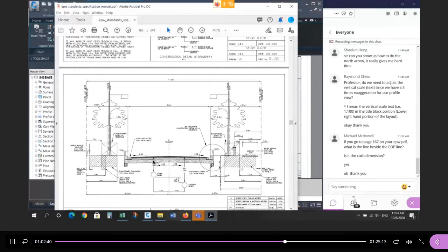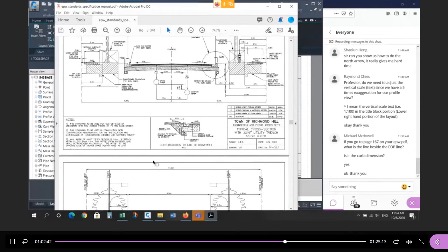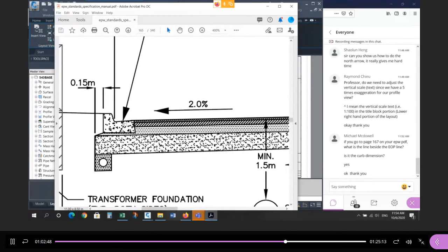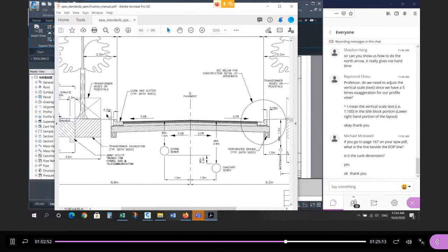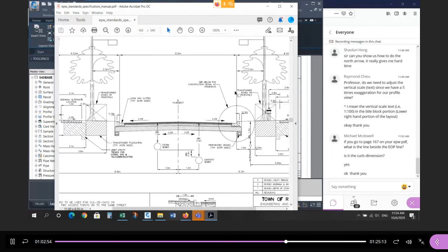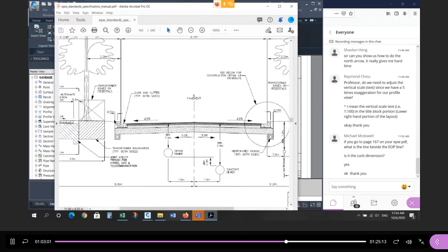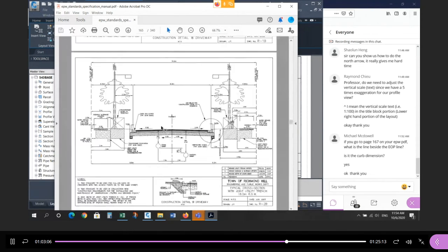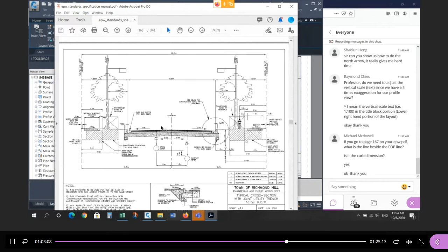This one, okay, local roads and collectors aren't that big a deal. But if you go to a freeway or an arterial road, the pavement width actually is from edge of asphalt to edge of asphalt. That width of the gutter is not included in the pavement definition. So you really have to pay attention to the standard. The term pavement is not always the edge of asphalt, is not always the gutter line. It depends on the standard you're using. In Richmond Hill, it means gutter line. I'm not doing that to confuse you. That's just the language that's used, so you have to get used to it.